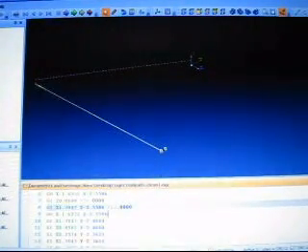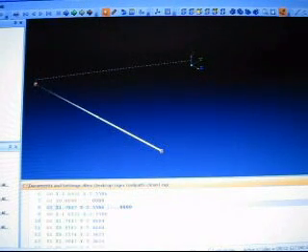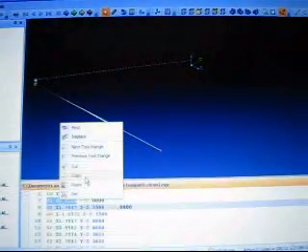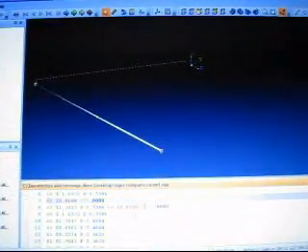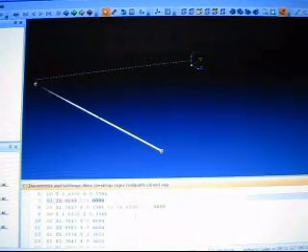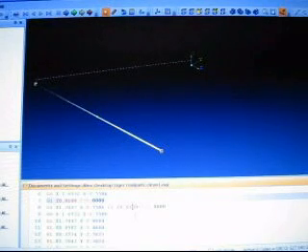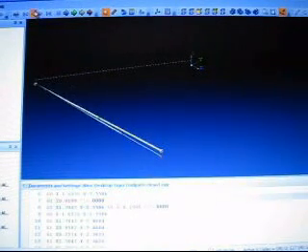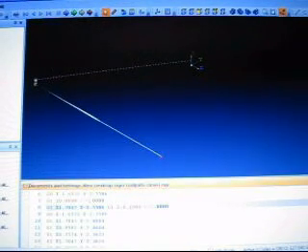and paste it. Okay, but on the previous line I want to add a depth to it. So I'm going to take this line right here and copy it and paste it right there. What I want to do is just modify it. I'll make it a negative value first of all, and then I'm going to make it 0.1 of an inch. So I'm going to ramp down 0.1 of an inch, and I'm going to do this successively.